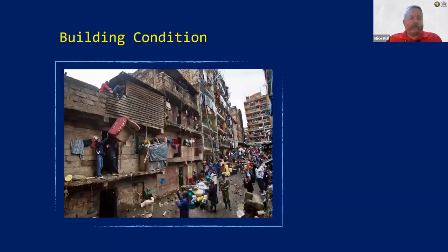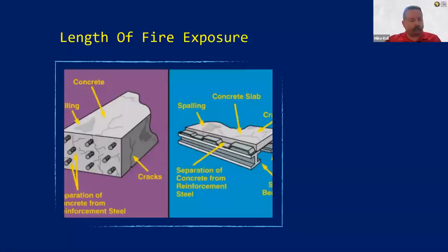When the building becomes involved with fire, what kind of hazard could that pose to you when structural supports were removed by somebody living in the building illegally? Maybe you think this is an abandoned building, but it turns out that people have gotten in there and hooked up illegal electrical connections. So you're expecting that there's no power in the building, but someone has rigged some wiring in there. So lots of different things that you may need to be cautious of with the building construction as we're evaluating the building as part of our scene size up.